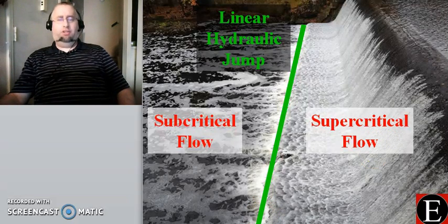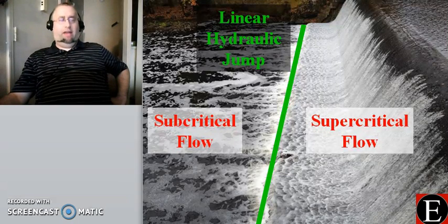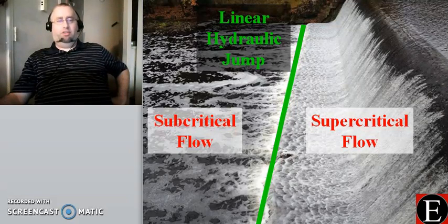Now, I did want to show you a movie of this river actually flowing, and the thing that you want to look for is that the location of this hydraulic jump is essentially fixed in space, and that's because the volume flow rate over the spillway is essentially fixed, and so the hydraulic jump doesn't move upstream or downstream as a function of time. And it turns out that we will see the same thing with the radial hydraulic jump. Once we fix a volume flow rate, the radial hydraulic jump will assume a particular radius that won't change very much. So let me show you that video.